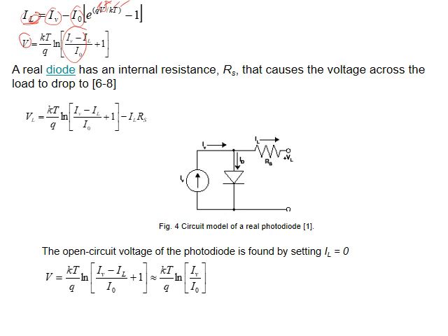Now one more issue: you know the two contacts, positive and negative, coming from the cell. At the end, these are materials. They have resistance, even if it is small, but it's a fact. So I can consider it as a series resistance, and here the load. So there is a voltage drop across the terminal. I can account for it by subtracting this part from the total voltage. Now, if we have open circuit, no current in the load, then this part will be gone and this part will be gone, and the equation is simplified for the open circuit situation this way.